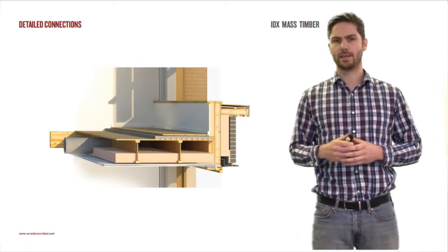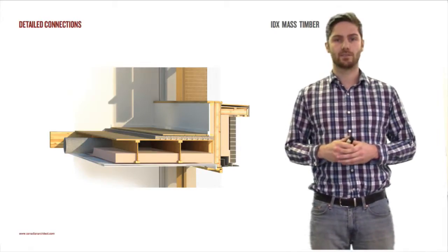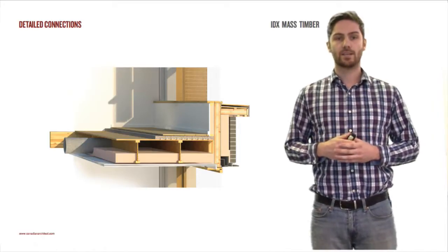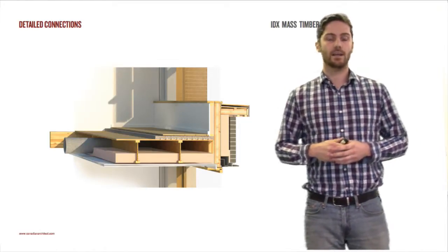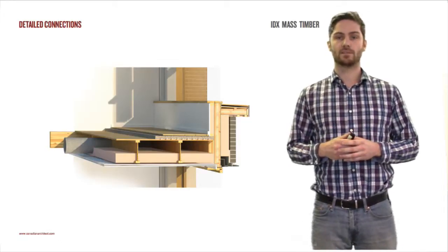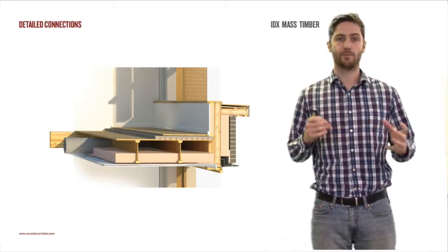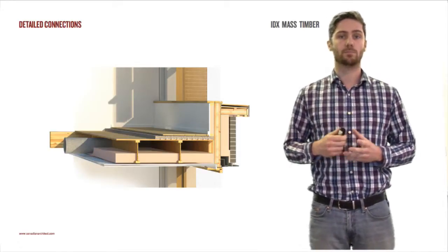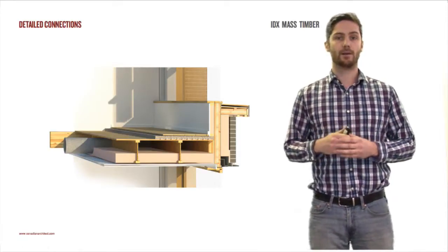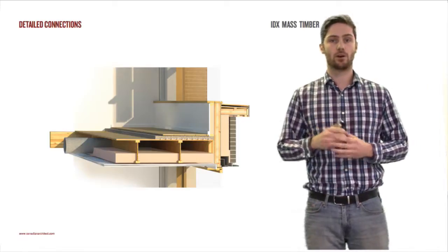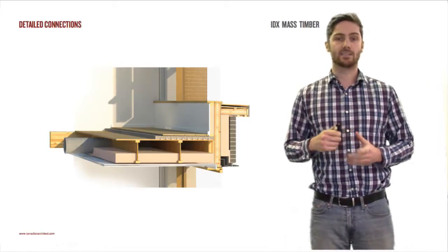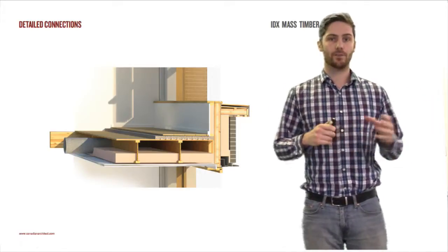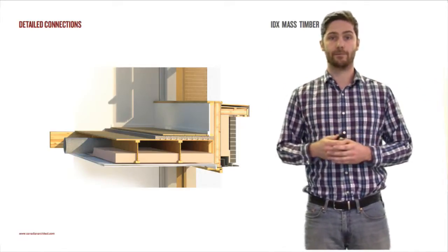Also, furthermore, I want to just point out that there's going to be two types of construction that you see here. And the two different types are balloon type construction and platform type construction. Now the difference is for balloon type construction, the diaphragms are being hung off of some sort of hanger that's connected to either the wall or the column, whereas platform construction, the diaphragm gets placed on top of either the column or the wall, and then the next column or wall is built off of that. And so there's a bearing pressure on the column or wall due to the diaphragm.